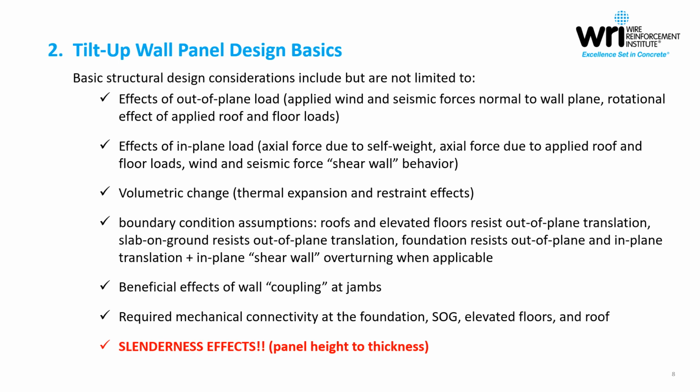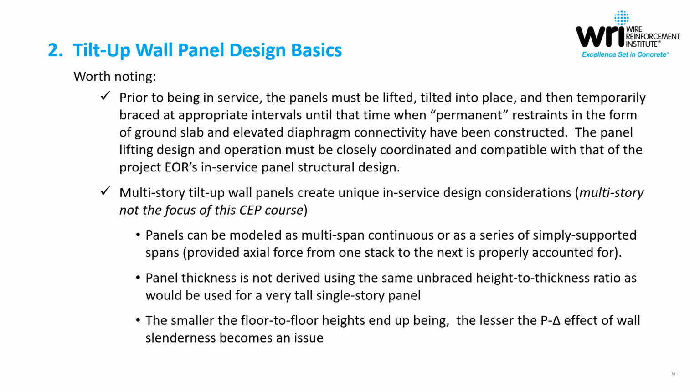Last but definitely not least, and a pretty heavy focus of this presentation, is slenderness effects. So we're talking about panel height to thickness. Wall slenderness can of course impact P-delta effect, which can have a magnifying impact on both the flexural demand and of course the deflection of the wall panel itself. So we'll get into that quite a bit here shortly.